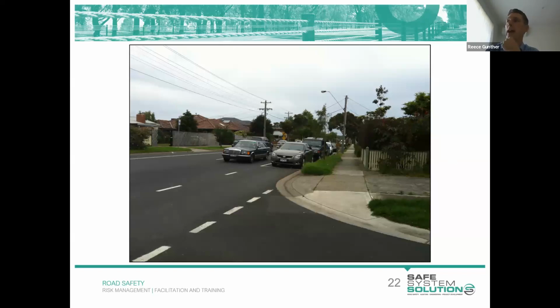And another one would be to remove vegetation. Fantastic, very observant. Yep, there is a tree there. Now, most people would probably say that tree, oh, it's a stick, it's not going to impact sight lines significantly. What people fail to recognize is that that tree over time will grow, and in doing so, the sightline issue will get worse and worse. So it's important to highlight that it's not just at this point in time, you're looking at some point in time in the future where that may be an issue.